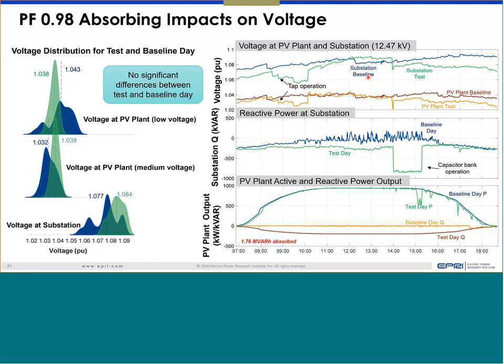So, yeah, there is a possibility that if your outage is somewhere not immediately at the terminal of the plant, somewhere upstream, and you have load between the outage phase and the plant, and the plant has a certain type of transformer configuration, and there is a load present, then the inverter may not see an abnormal voltage and keep operating. That we call single phasing, and I believe for most utilities, for larger scale plants, either the DR has to demonstrate that it can detect it, or it has to put some negative sequence relays to detect that and shut down the plant.